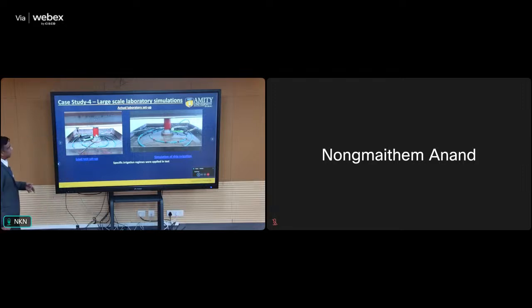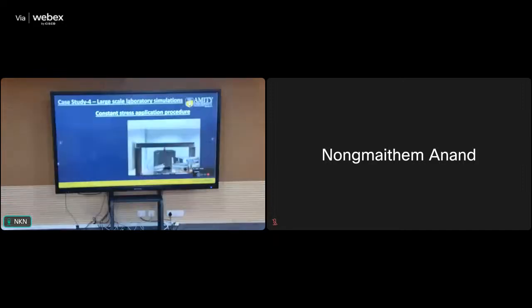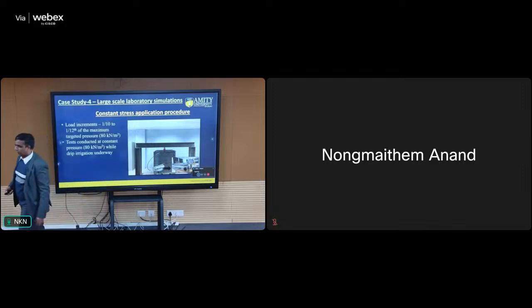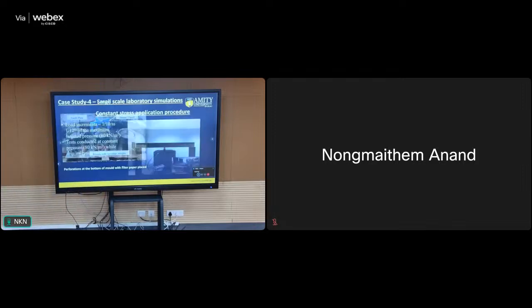So that is what we did in the plate load test. We calculated the stress that is required to be kept on the particular soil. As the water is dripping into it, as the soil is losing strength, this stress will get reduced. But when it gets less, we give energy to it and make it constant again. Understand? That is how we did the test. So this is the mechanism we used for maintaining the stress constant, on a large scale.